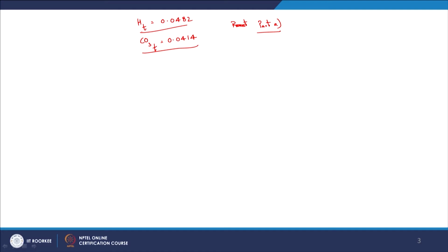And this is what I believe we calculated from part A. And now, what is the new aspect that we have now? We have additional acetic acid, HAc, at a concentration of 1500 milligram per liter, right. So, I want to convert this into millimolar units, and I think earlier we calculated the molecular weight of acetic acid as 60 grams per mole, right.